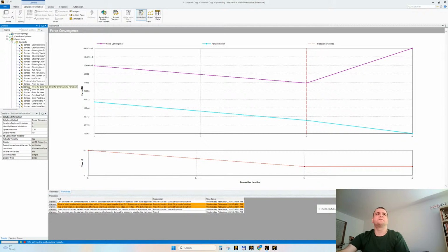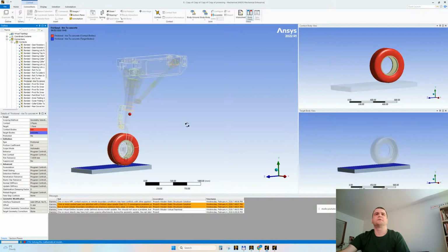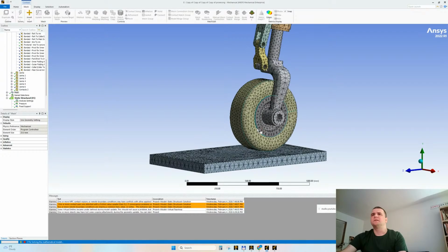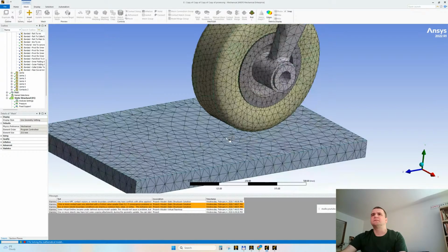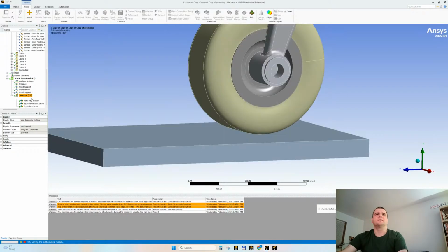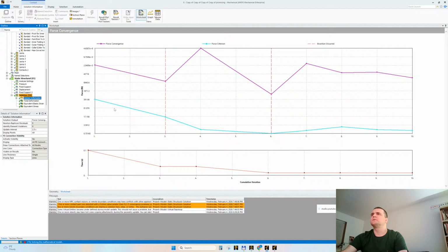Do I still have that frictional contact? Yes, I have it here. Yeah, this is a problematic contact. Let me press adjust a touch. Let me change adjust a touch. It can only help. And apply a pinball radius. Yes, let's apply a pinball radius.